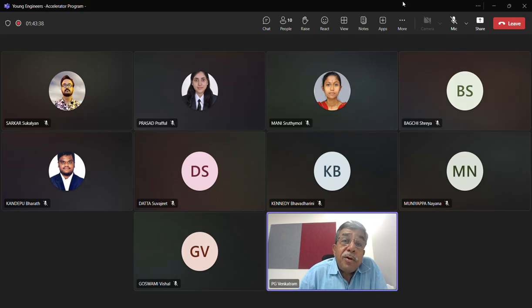Though we have seen a number of failures in the columns. A number of failures have been in columns. That means as far as the lateral phenomenon is concerned, it's a very real observed phenomenon, whereas for the vertical phenomenon, observation shows that it is significantly non-governing. So it has less to do with the gravity load direction. But my question to you comes back to it: why is it that we never see a problem in the vertical direction seismic?